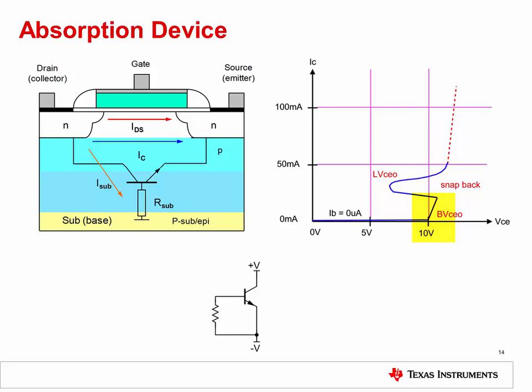Collector current will increase until a point where a snapback takes place. Beyond the snap region, current again begins to rapidly increase. If there isn't another source of resistance in the transistor's path to limit the current, it can increase to the point where the thermal generation results in excessively high temperatures and transistor meltdown. Usually the emitter ends up spiking through the base and shorting to the collector, forming a permanent short circuit.